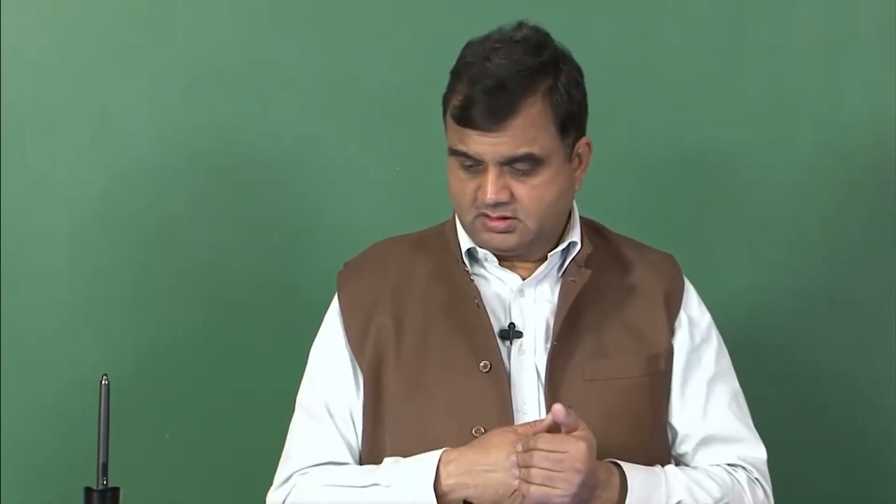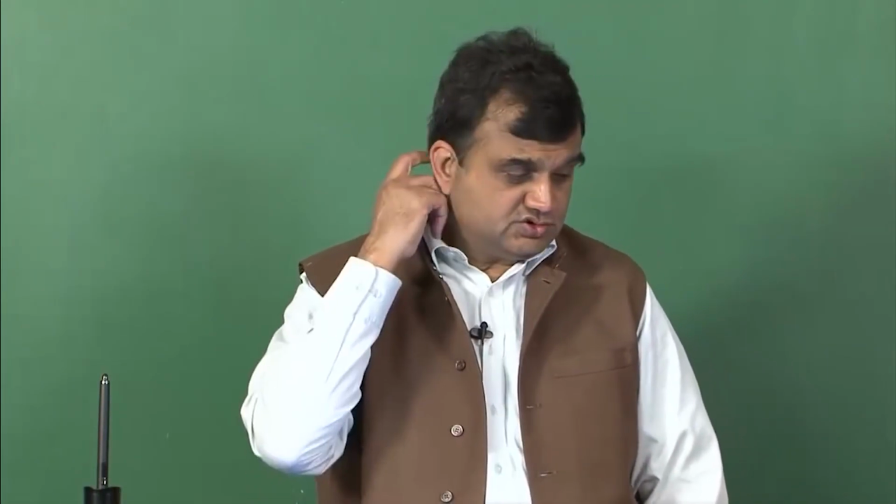Yesterday we had just started discussing graphite fibers, and I had mentioned that graphite as a substance has a layered structure. Because of its very nature, the structure is such that it has very high in-plane modulus, and out-of-plane modulus is not that high. The other thing about graphite, again because of its structure, is that it is very easy to break along between the planes. So, that is why graphite fibers also tend to be brittle in nature.